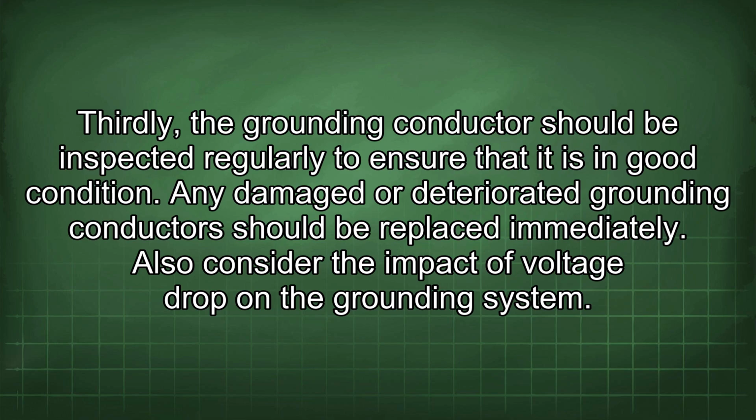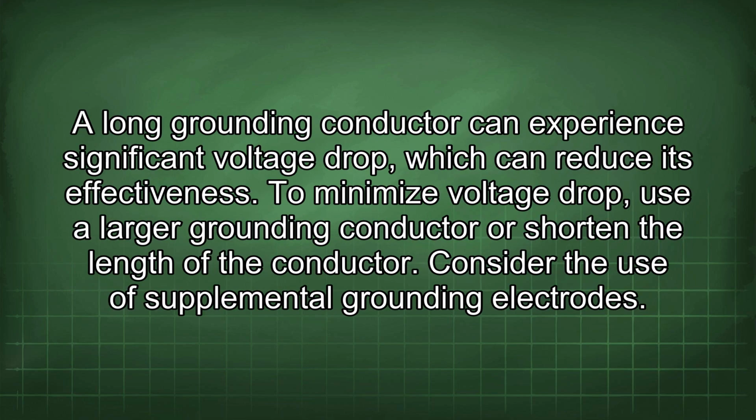Also consider the impact of voltage drop on the grounding system. A long grounding conductor can experience significant voltage drop, which can reduce its effectiveness. To minimize voltage drop, use a larger grounding conductor or shorten the length of the conductor.